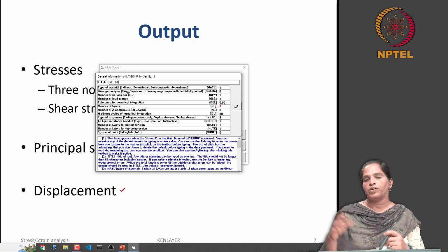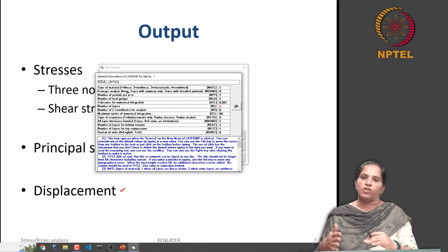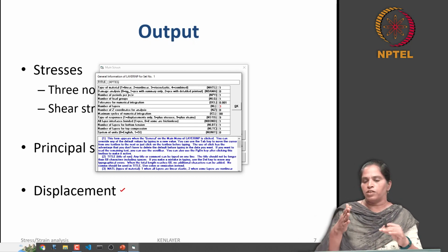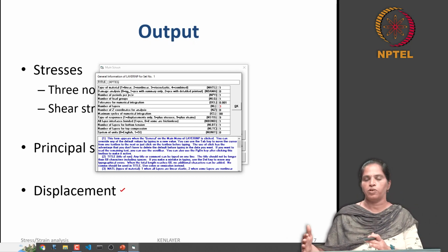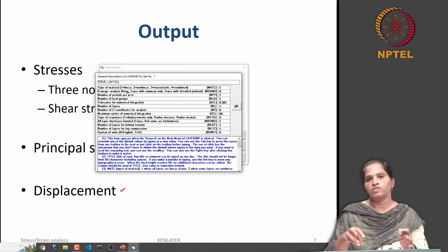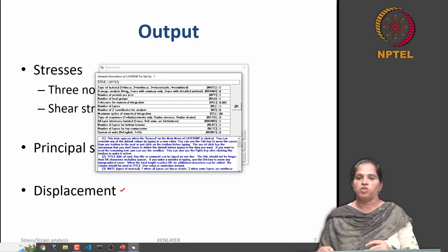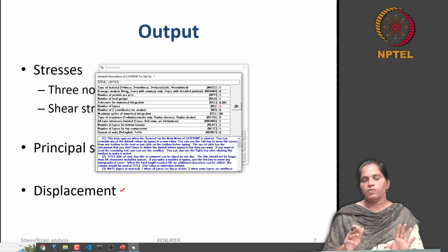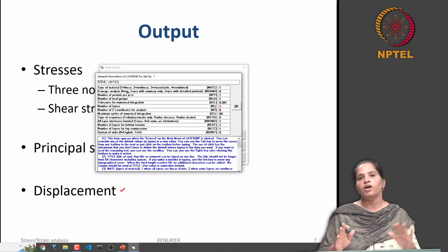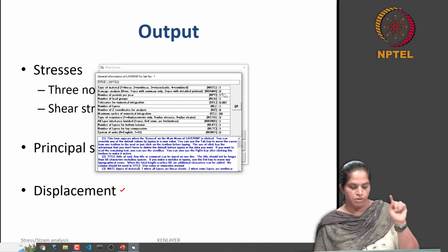For example, if you take a subgrade layer, you have a different modulus of a subgrade layer for every month. That is, in winter you have a different modulus value, in summer you have a different modulus value. So this allows us to define different modulus for different periods. You can go up to a maximum of 12, that is one modulus per month in a year. As of now, we will give only one modulus, and we assume that the modulus value is going to be constant throughout a year. So here the number is going to be 1.